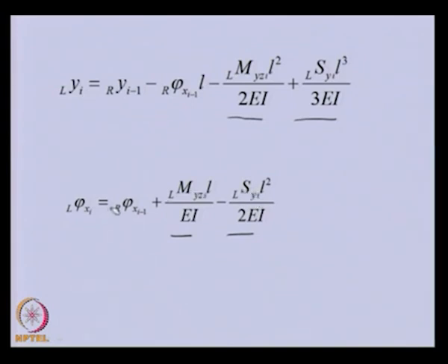When we are giving a linear displacement to this, there is no change in the slope, because in this particular case, if we are giving a linear displacement like this to the shaft, there will not be any change in the slope. This is in the second case when we are considering the shaft as rigid. But when we are giving a change in the slope like this to the rigid shaft, we will have the same amount of slope at this end also. So, whatever slope we are changing at this end, the left hand and right hand will have the same angular displacement. So, this is that particular component.